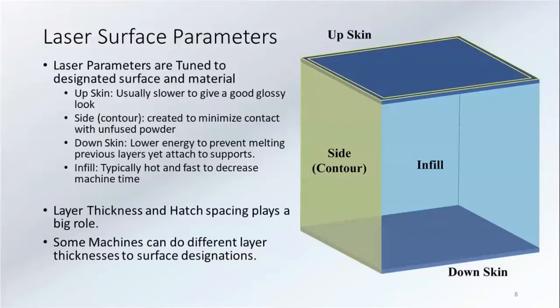I'm really not going to knock a machine here because I've seen them all produce very, very good parts. Nuance comes in where some of them tend to work better with heavier metals, or some with lighter metals, like an aluminum versus an Inconel. A lot of that comes down to the recoater you're using and the powder supplier you're using as well. So that's more where the nuance comes in. But when it comes to these types of parameters, it's pretty accepted industry-wide.